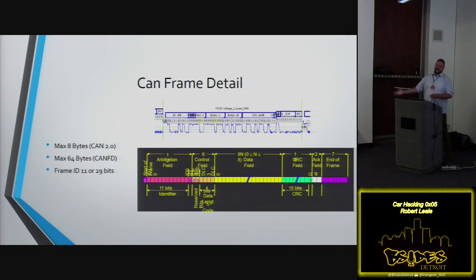If you guys look at TCP/IP, if you're familiar with that, each thing is just a bunch of bytes. Just here's 8 bits, next to 8 bits, next to 8 bits, and that's it. CAN bus works fundamentally a lot differently. It's not 8 bits next to 8 bits, except in the data portion. Otherwise, there are just individual bits that describe the arbitration ID, which is next to how big the frame is going to be, which is next to the data, which is next to the CRC.